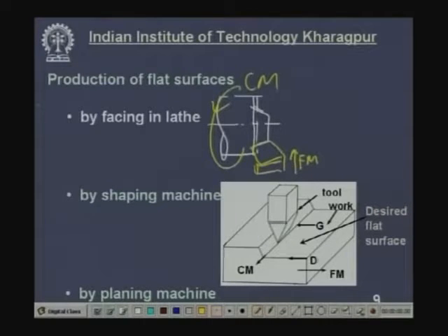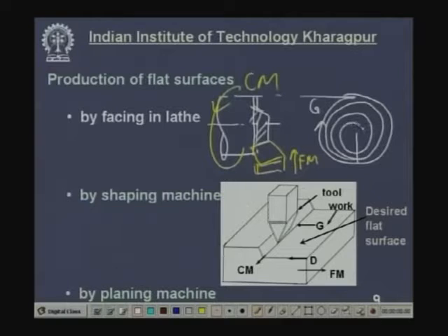So, if you look from this side, this is the workpiece, outer periphery. When this point is fixed, the job rotates, this is the locus of the contact point. So, this is generatrix. Now, the tool moves inside and removes this material gradually. That means the diameter of the circle is gradually reduced and the metal is totally removed.